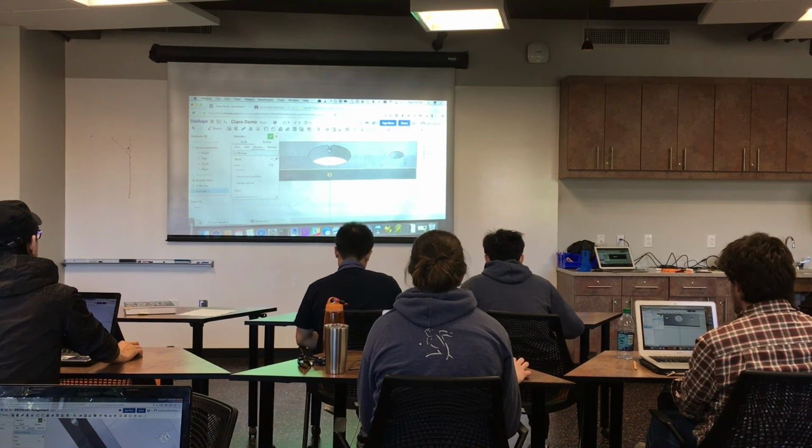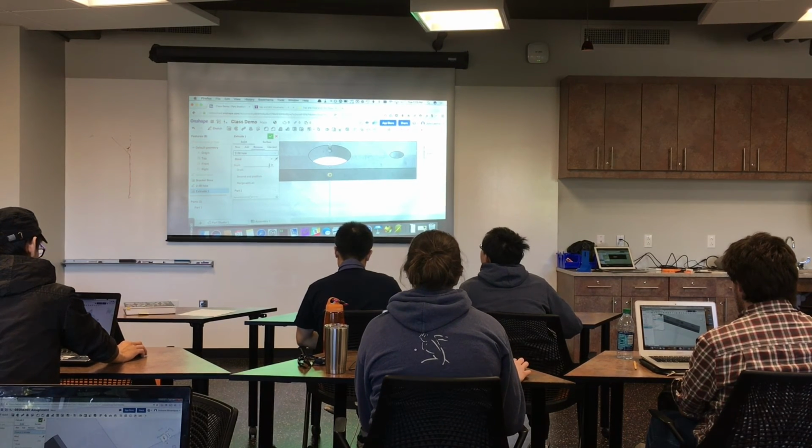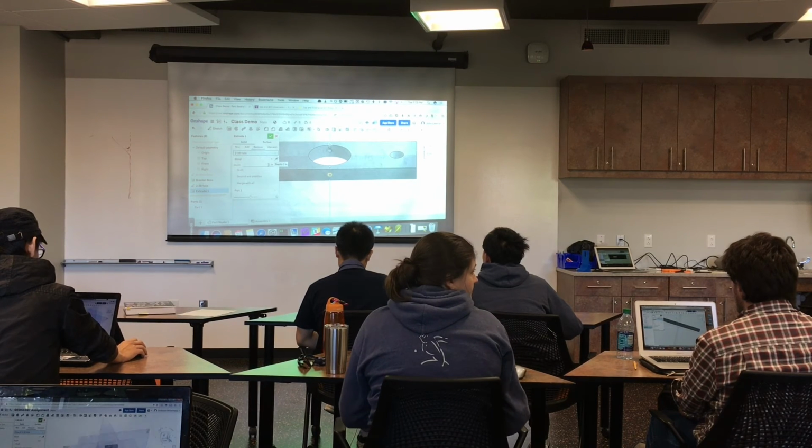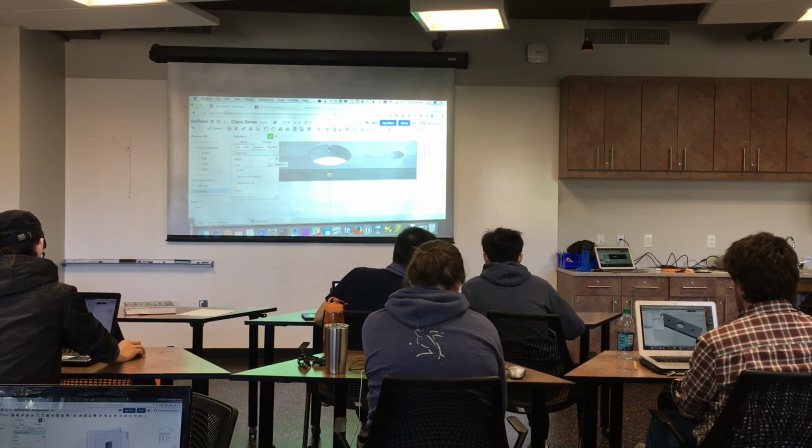And now it's going an inch into the part, which is putting it all the way through here and out over here. That's not what we want either. We could specify a depth, but remember that would kind of go against design intent. If we change the part to be much bigger, maybe it wouldn't be a through hole then.